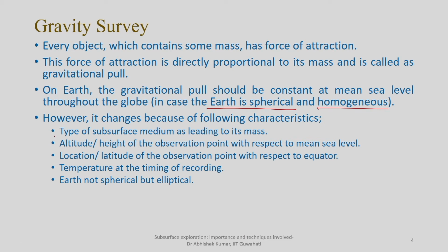One among these, which is primarily of our importance, is the type of subsurface medium, because if the subsurface medium is going to be lighter, it is going to reduce your gravity. If it is going to be denser, it is going to increase your gravity value. Though the difference in increase or decrease will be very small in comparison to the acceleration due to gravity, the normal value, there will always be some difference, which is an indication of change in the mass of subsurface medium, change in the density of the subsurface medium.